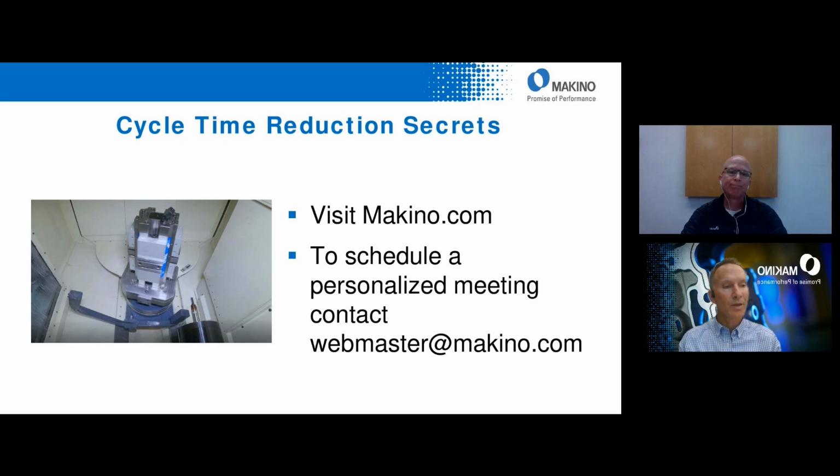Yeah, okay. And one other question that just came in. This one is a little bit different, but I think we'll go ahead and touch on this. And like we've talked about, Mike, we've got a series of webinars where we're going to be talking about a lot of different options and features for reducing cycle time. So this one might be in one of our other episodes, but let me go ahead and let you know what this audience member asked. Wants to know, would it be possible to do a tool change or positional move while the pallet is changing? That's a good question. I believe you can do tool change during pallet change.